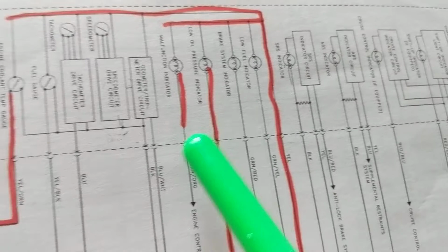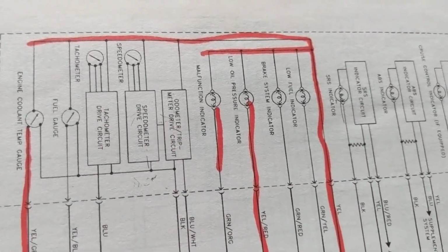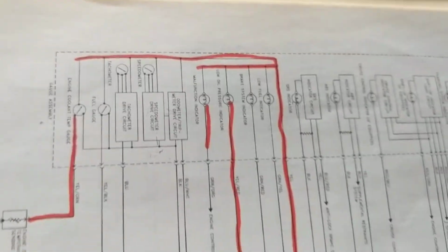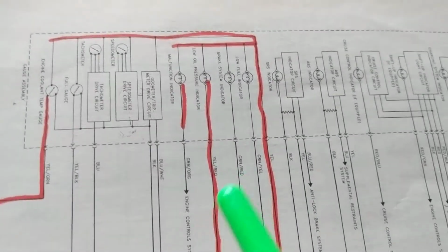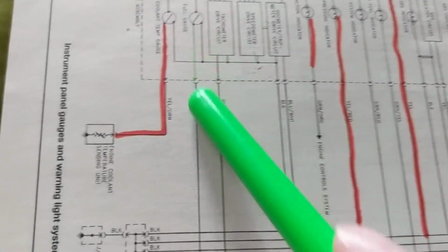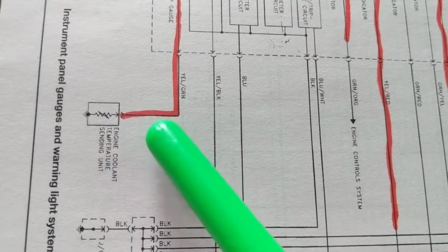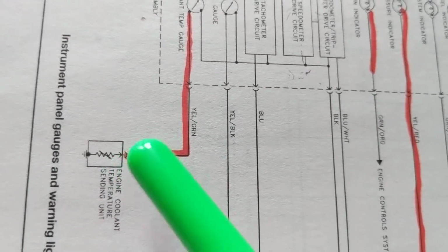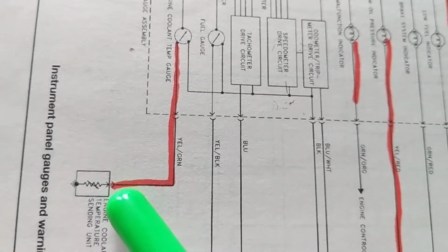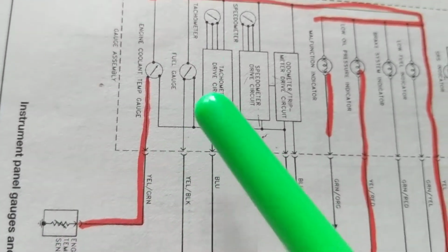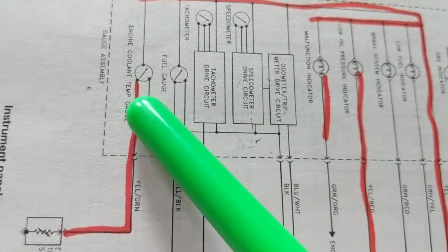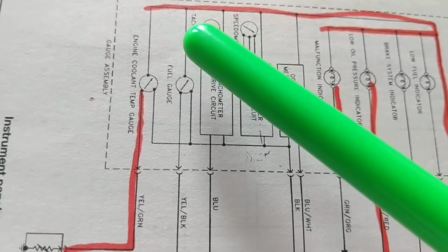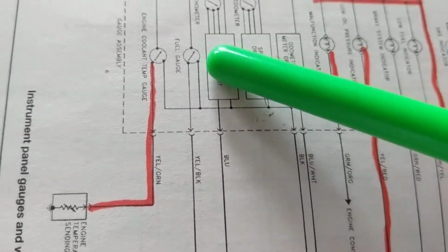ABS, cruise control. Then we have the gauges. So the gauges are here, and the gauges also need one thing that I stress, 12 volts. All these things work on 12 volts, if you remember or recall. So it's the same concept. Engine coolant temperature goes by a thermistor, right? This thermistor, this resistance changes with temperature. It goes lower. They call it negative coefficient. Anyway, that will give you on the gauge the coolant temperature, how hot the engine is getting. Usually we want it in the middle. Sometimes you have the numbers, 210, sometimes you just have the middle.